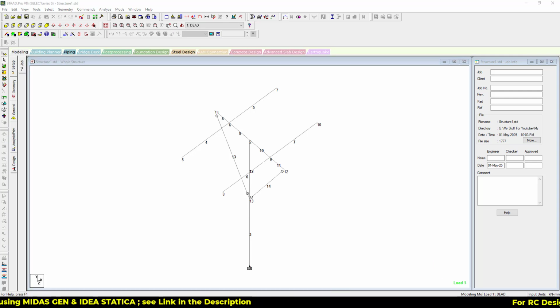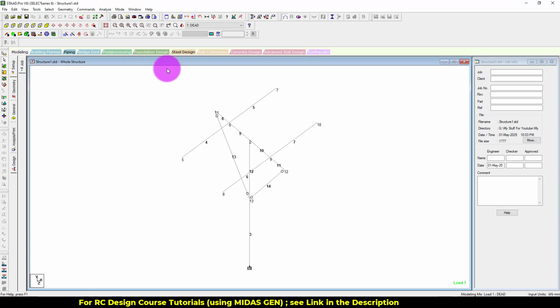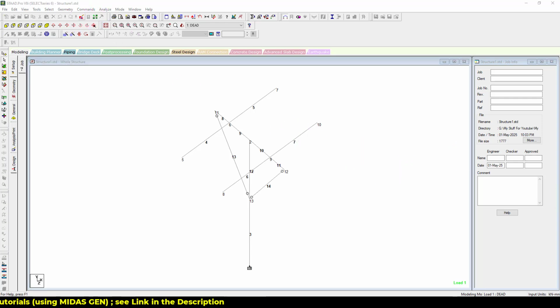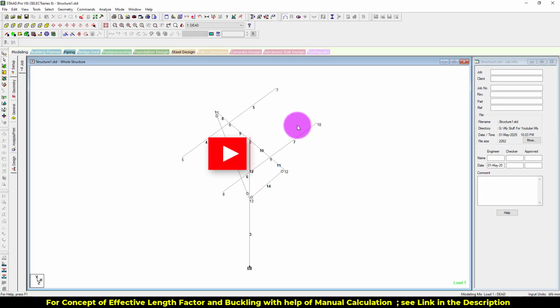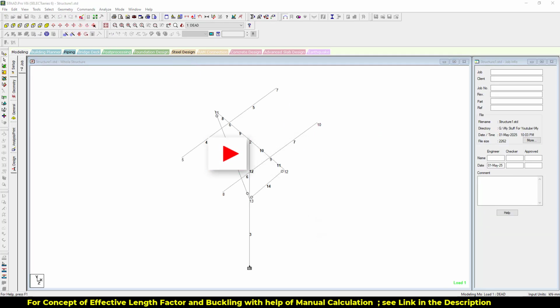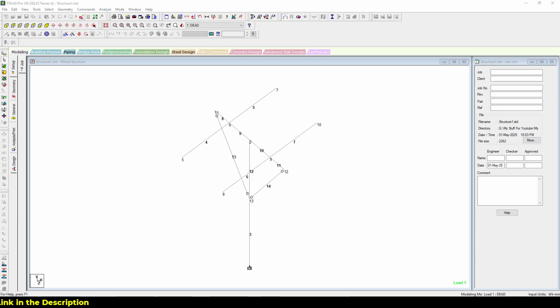First we need to generate load combinations. I have already generated load combinations using ASCE 7-05 because we are designing these members using the old code. So just copy the strength load combinations and paste them under the last loads value and then okay, 101, 102, 103 and so on up to 109. So these are the load combinations. Now one more thing, we need to tell the software to check load list 101 to 109.